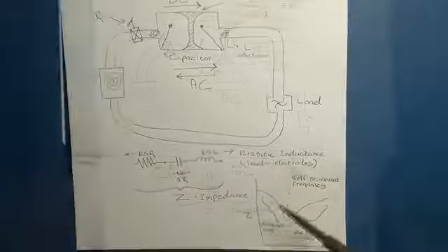But then as we start increasing the frequency, impedance starts going up again. What's that due to? We've said that's due to the inductance of the electrodes or the leads. That's why I've got these inductors here, or let's say pretend the steel wool in the pipes here.